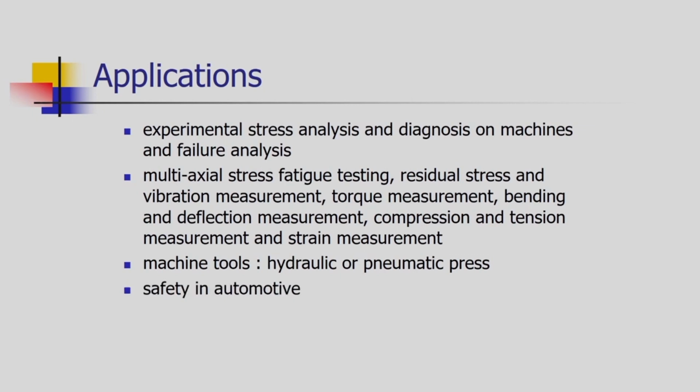Some applications are there in front of you. Basically, strain gauges are widely used in experimental stress analysis. So, those who are carrying out MTech or PhD projects in mechanical manufacturing, basically in experimental mode: for stress analysis and for diagnosis of machine tools, strain gauges are widely used, particularly to measure the forces. Moreover, they are used for fatigue testing, stress analysis, vibration measurement, torque measurement, and bending and deflection measurement.